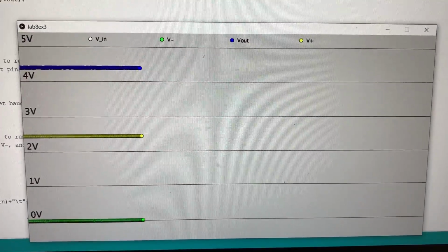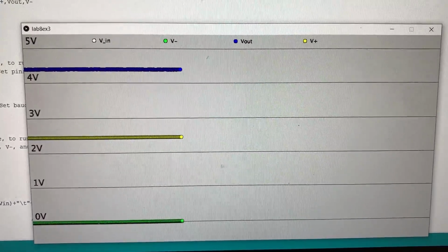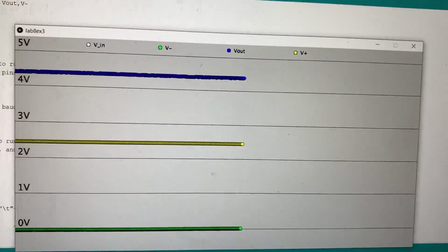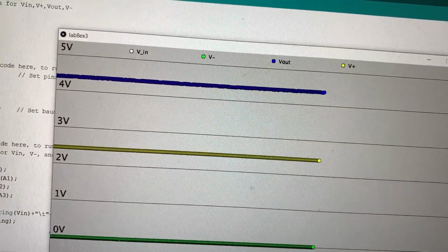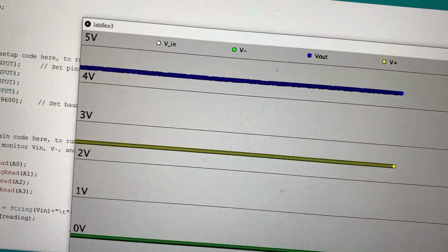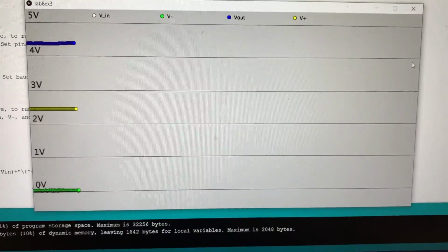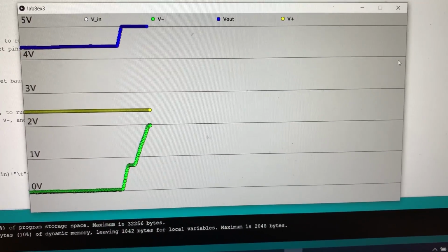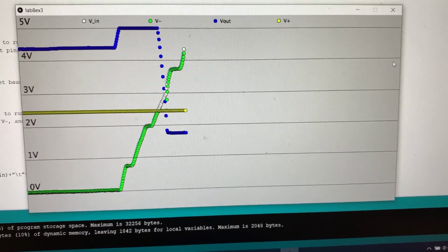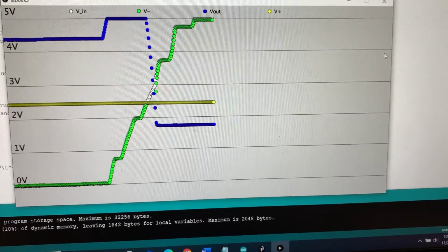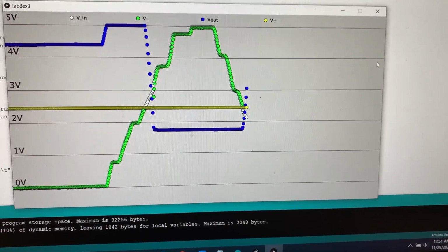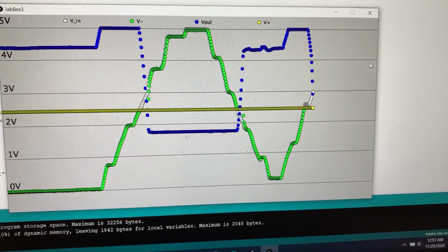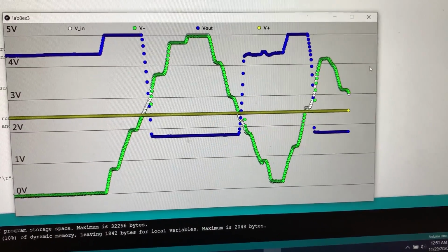So this is our output for our circuit. Right now, Vin is at 0 volts, or we can refer to it as -2.5 volts. What the integrating amplifier does is it basically outputs a voltage equal to the time integral of the input voltage of the circuit. You can see Vin is at 0 volts right now. Then when I cross 2.5, you'll see that V out inverts because, if you remember from our analysis, the gain is negative. Then we cross back down 2.5, it inverts again. It looks like a charging and discharging of the capacitor.